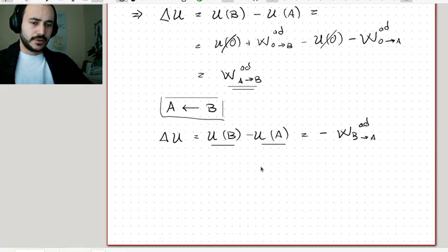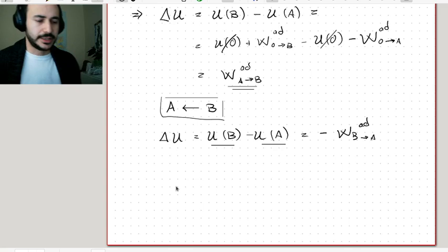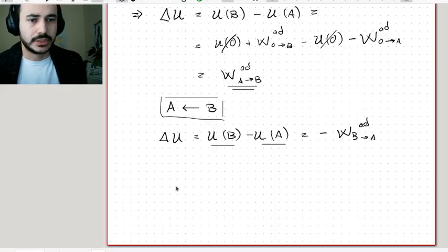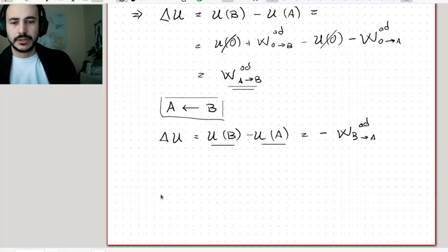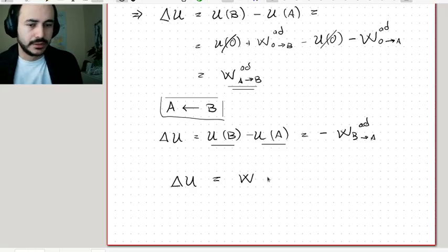So now the final comment of this first video would be that, imagine that our system, which is enclosed in these adiabatic, perfectly insulating walls, well, imagine that the walls are not such good insulators. So imagine that there is a little bit of heat leakage through the walls, even if it's tiny. Then what happens is that the change in internal energy must not be exactly equal to the work. It must be something more. That something more, we are going to call Q. Okay, so this is just a definition, really.